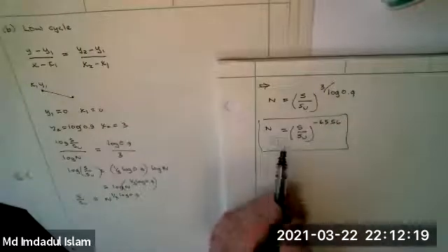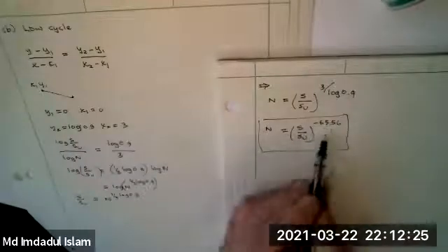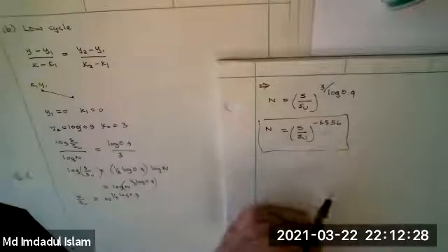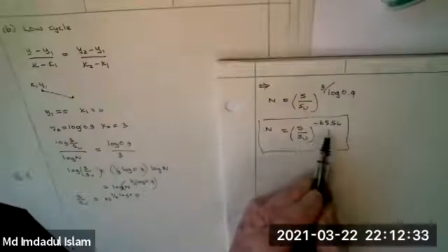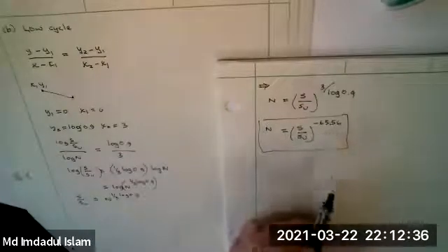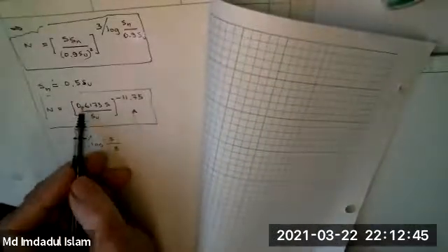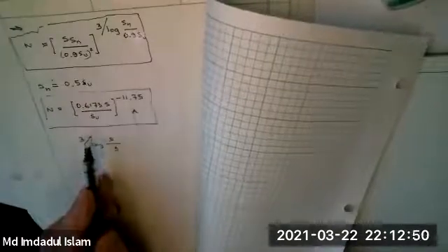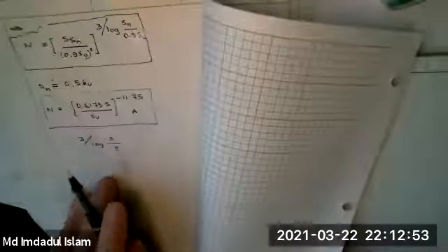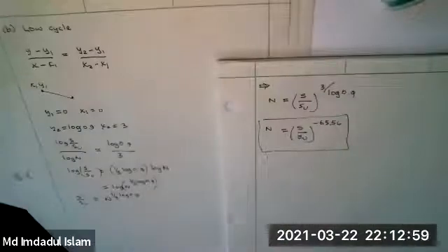Now, we're going to talk some more about scatter. There's a lot of scatter here. You want to be careful when you start using exponents. Okay, I'm going to give you exponents to 4 figures. That's good practice in engineering. You start messing with these things, you'll get very different answers quite quickly. So exponents to 4 figures is reasonably safe. You won't have any significant calculation errors. The same thing for this exponent. It's probably not so necessary to have 4 figures there, it's just kind of consistent. But these N, the number of cycles, are really only going to be good to 2 figures. It's just that if you're changing this, you'll change those 2 figures. Let me do an example.